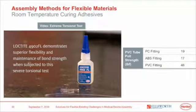So what you saw in that video was that the traditional cyanoacrylate actually broke at the bond line after about 4 rotations. Compare that to the highly flexible CA that you saw towards the end of the video, that after more than 30 rotations on the lathe, it actually broke, but it yielded substrate failure, where the bond didn't fail, but the tube itself had actually failed.